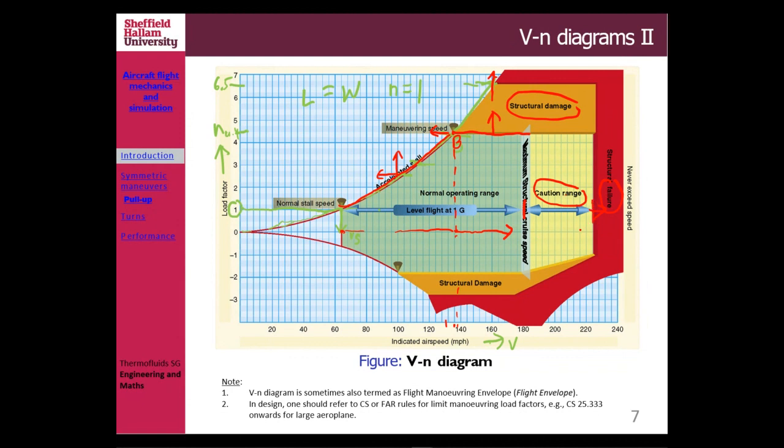To avoid those things happening, usually we have a factor. People use 1.25. So if you put, like, Mach 0.78 as your cruise speed somewhere there, but the maximum structure cruise speed is maybe 0.85 or 0.86, then you multiply that with 1.25, and that is your maximum structure failure speed. Beyond that, structure failures could happen, which means your aircraft will disintegrate.